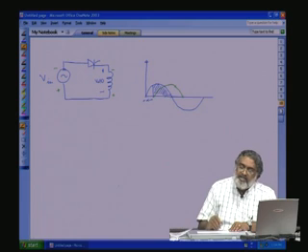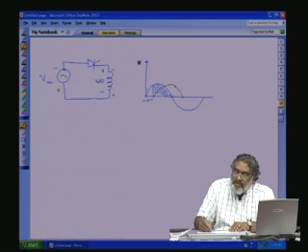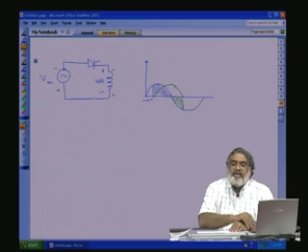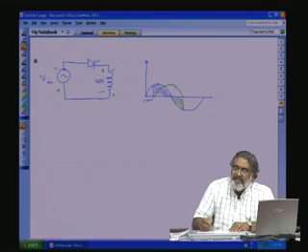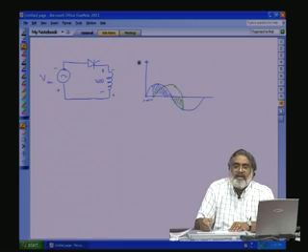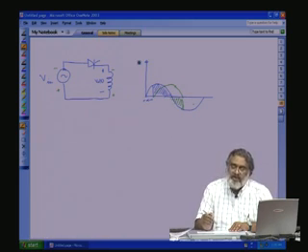So, what is the disadvantage here? During the negative portion, up to this point also, the voltage appears across the load. Now, compared to our previous equation, the relation between firing angle and the DC output we cannot apply here, because the negative portion has also come in. So the previous equation of output DC with respect to firing angle is no longer valid here, because the thyristor is conducting in the negative direction also.